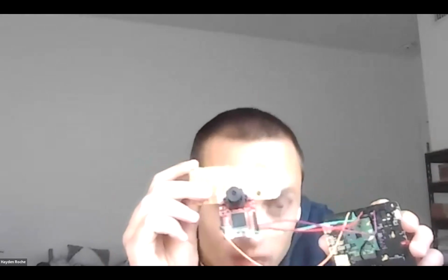And also it uses an OpenMV cam. So here's my jury-rigged setup. If you can see this, this is an OpenMV cam. So it comes with a camera and a lens and a little STM32 that runs MicroPython, which is a very stripped down version of Python that can run on microcontrollers. This is just a wood shim that I was using to mount the thing, which I'll show you in a sec. And this is, again, a note carrier A with a note card on it. And they're just connected to each other via I2C. And I also have the note carrier providing power to the OpenMV cam. So note carrier A, good choice if you have a non-Feather MCU that you're targeting.